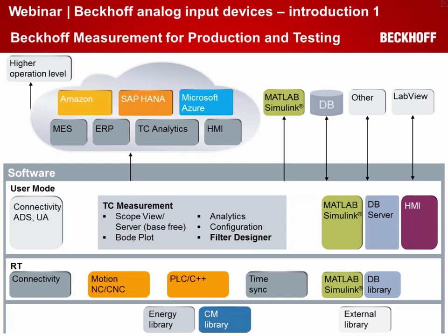In the real-time environment on the IPC, which is realized by the EtherCAT real-time software on every standard IPC, we have the motion functions, NC, CNC calculating for the axis, and of course PLC, C++ coding for real-time code. Real-time in Beckhoff means that we are talking about cyclic work of tasks.